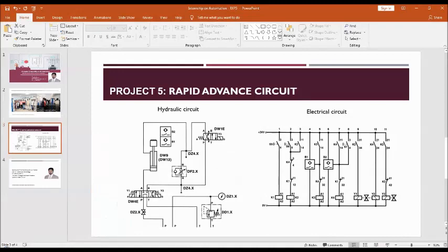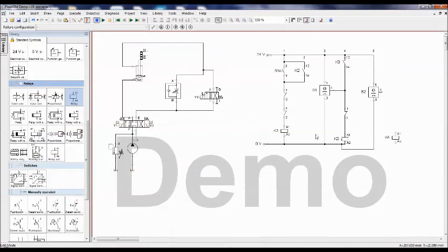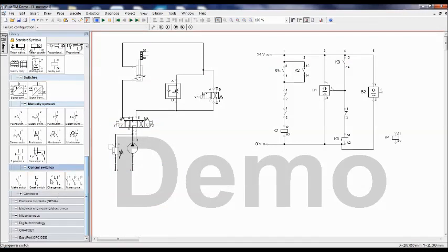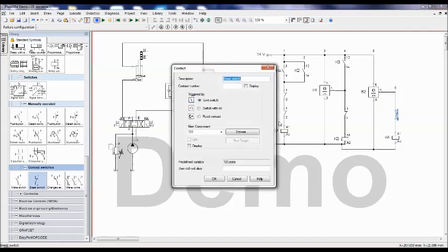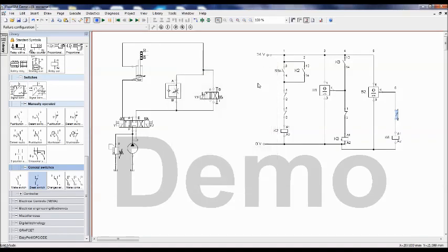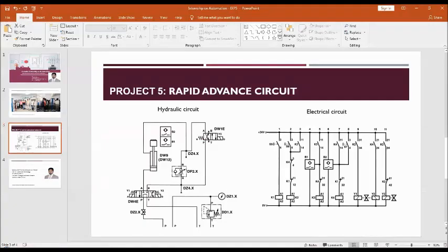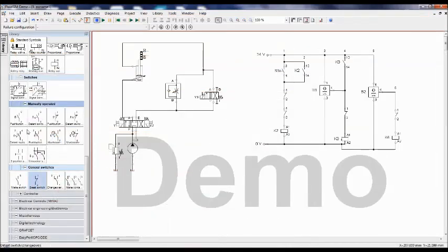Again K4 is connected through a K1 normally closed contact. So a normally closed contact should be used. This is K1. I can link it to K1 because K1 is already available. Okay, sorry, I have not taken K1. So let me take K1 first. That is S5, connected to K1 in the beginning. That is one more switch. This is actually used for reset. This is actually used for a reset application.